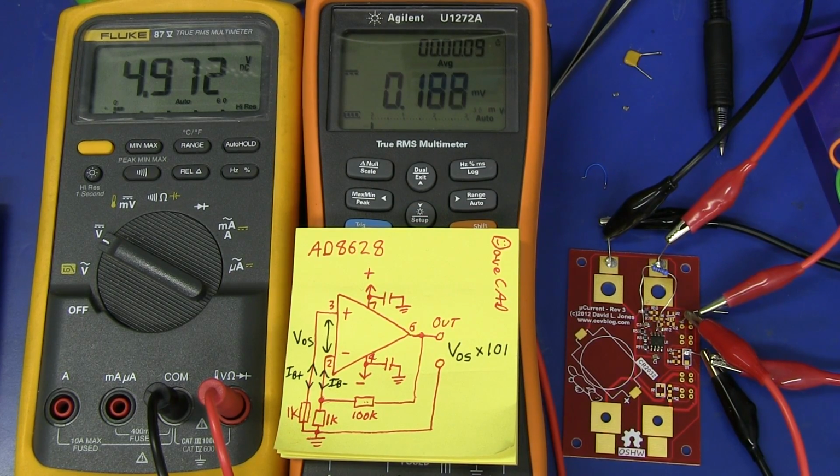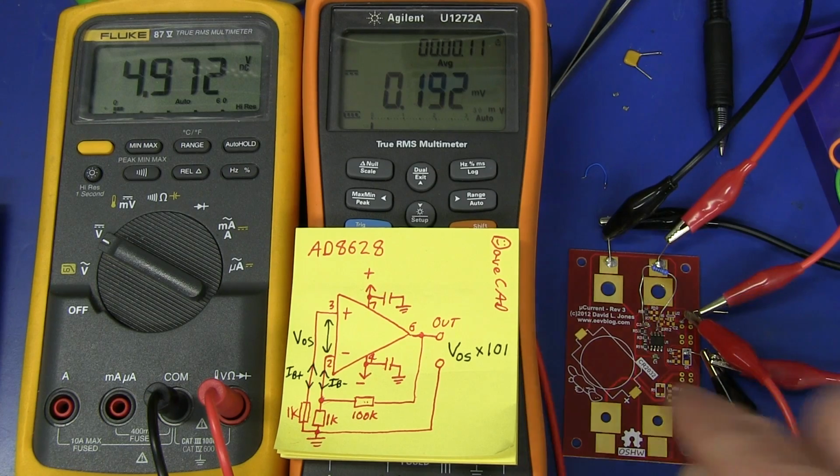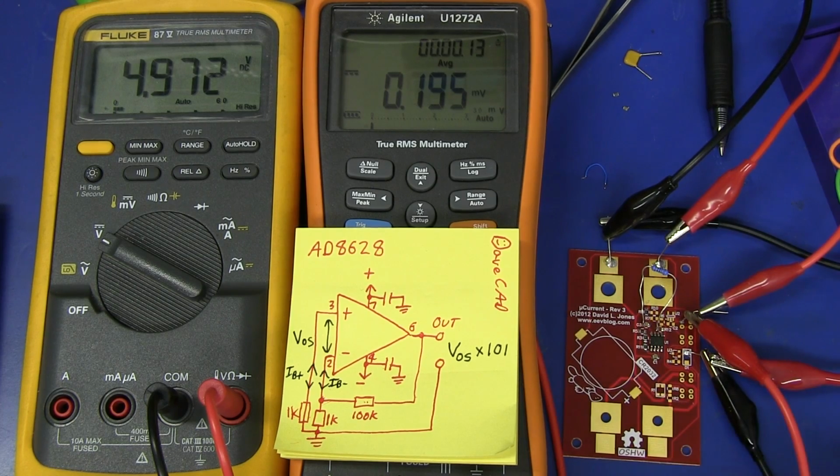180. Oh, I think it's changing because there's probably still something a bit warm there, perhaps from my soldering iron. You've got to be careful of that. That can be a trap for young players when you're measuring critical stuff like this and you've just soldered it. The chip could be hot, the components could be hot, whatever.